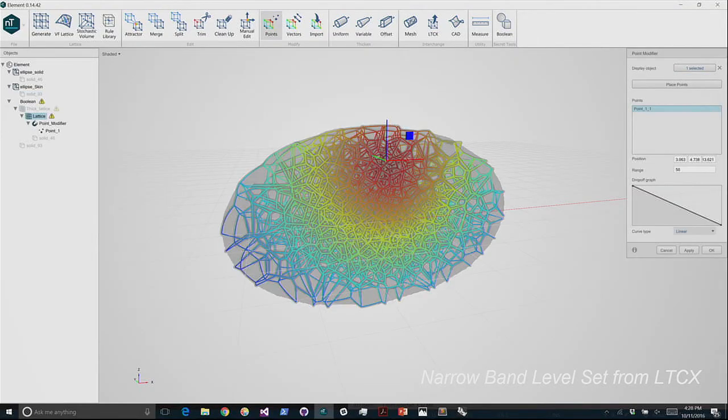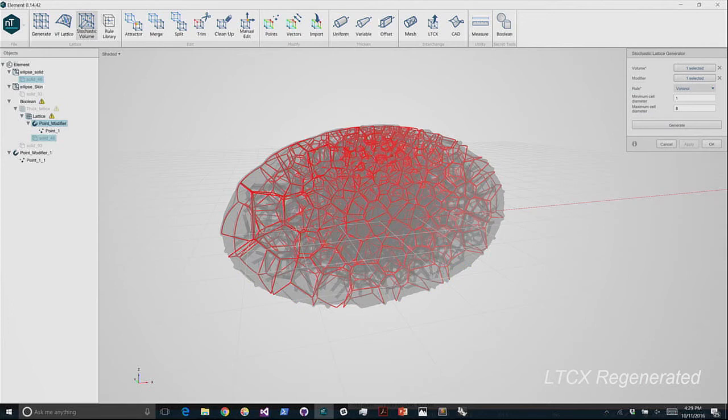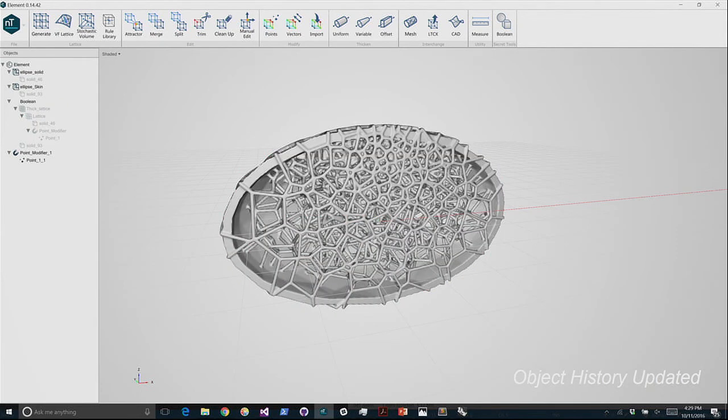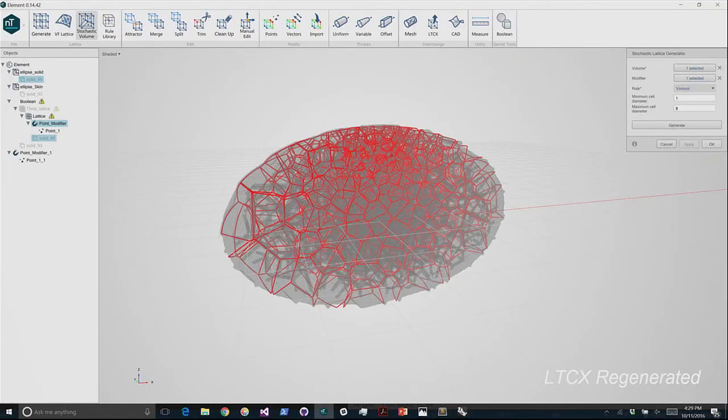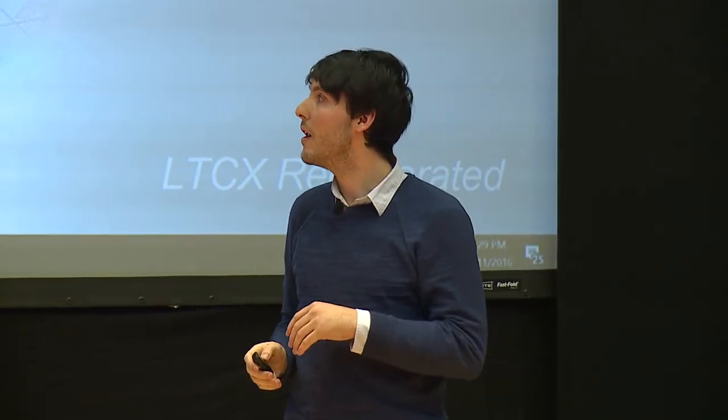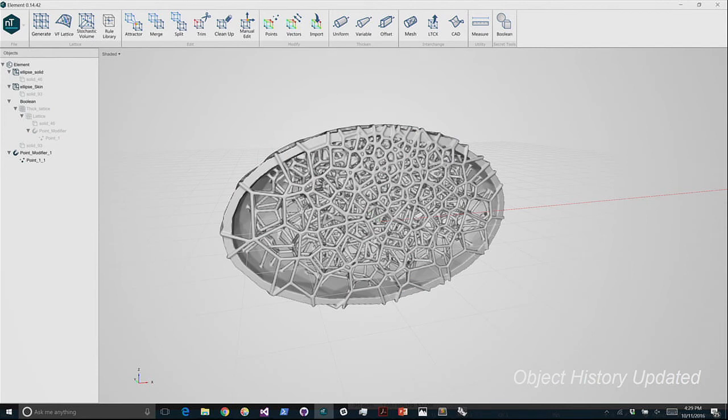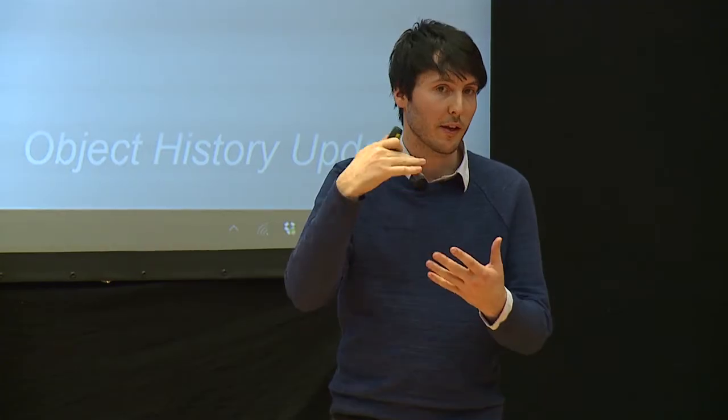And so we could go back, double-click open in the history the node for the modifier, move the modifier up, and then recalculate the entire process. Right now it's not one button click. You can see the yellow warning symbols that show you dirty parts of the tree, so you have to go back and open each one and regenerate it. But that's kind of nice too, if it's a slow process. But we'll have a way of just clicking a button and auto-generating the whole thing.